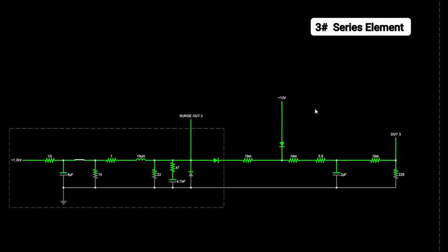So with nothing else on the board, that series resistor can play a really important component in helping your overall circuit. Again, whatever is on here is still probably going to be dead, but it can at least help. And to state the obvious here, I'm not going to be able to do it without letting this discharge. But a big thing to keep in mind with a series resistor especially is, depending on what your output load is, you want to make sure that this resistor doesn't load your circuit and clamp your current so much that the rest of your circuit won't operate.